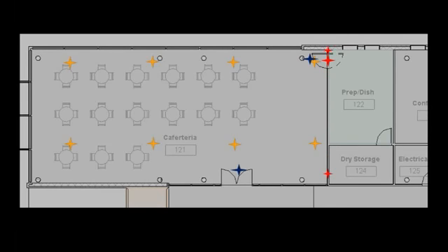So now for the thermostats. Again, we'll do the same thing, find one of the doors in the room. Now we're going to find the two endpoints for the wall that it's hosted on. Find the one that's longer and move it that way. Now we're avoiding putting it in that corner, usually the long way where it's open. So we'll go down that way a little bit. And then again, we'll get the normals to the wall. And now I'll ask, which one's closer to the center of the room? And that's how we'll decide which side of the wall to put it on.